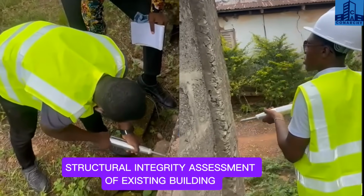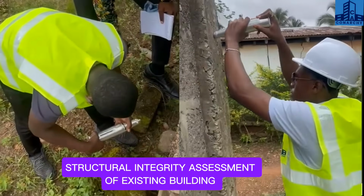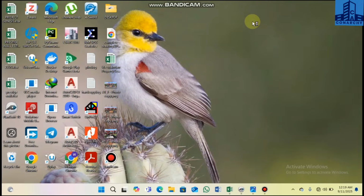So we have to have all of these details before we even start with the design, that's the structural design, even the architectural design as well. Also before making an estimate, we have to know whether the land is waterlogged, or whether there's clay in the soil. All of these are really important. That's why we have to do our site investigation before we start with everything.